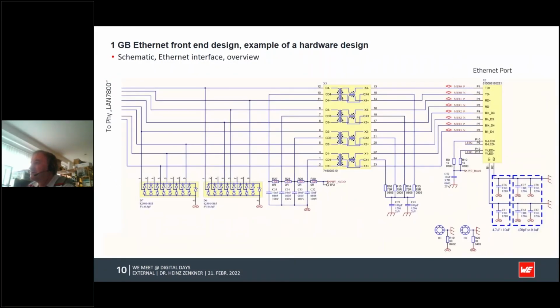We have here the cable connected. And all, let's call it transient voltages, transient currents, which are normally induced or impacted on the cable due to bursts, surges, or RF voltages regarding EMC immunity, they are converted here in the transformer into common mode, meaning on the secondary side here, you will have common mode disturbances on all channels.